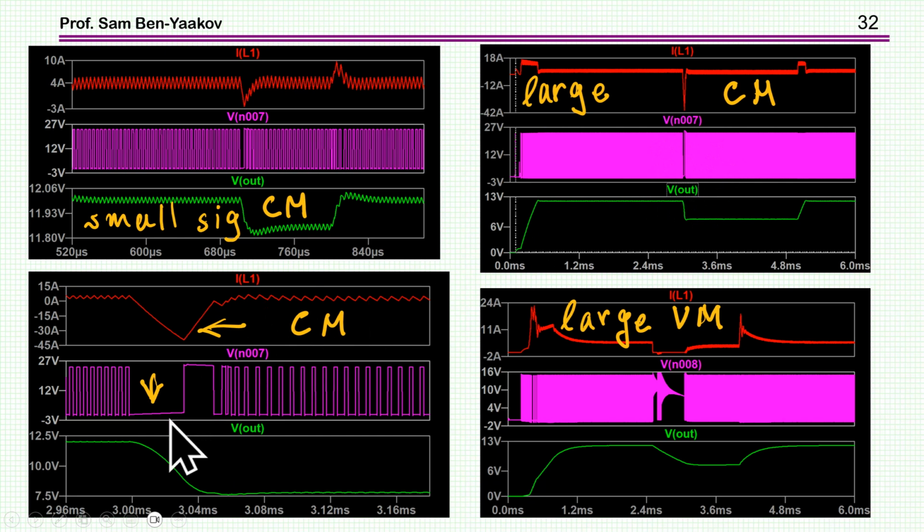Now, interesting, in this particular case, you see that during the drop of the voltage at the injection, the voltage at the midpoint is zero, meaning that the lower transistor is on, okay? And since it is on, there is a process of discharging the capacitor via the inductor, and you see that the negative current of the inductor goes to a very large value. And this is because the inductor is discharging the capacitor very quickly. See it here.